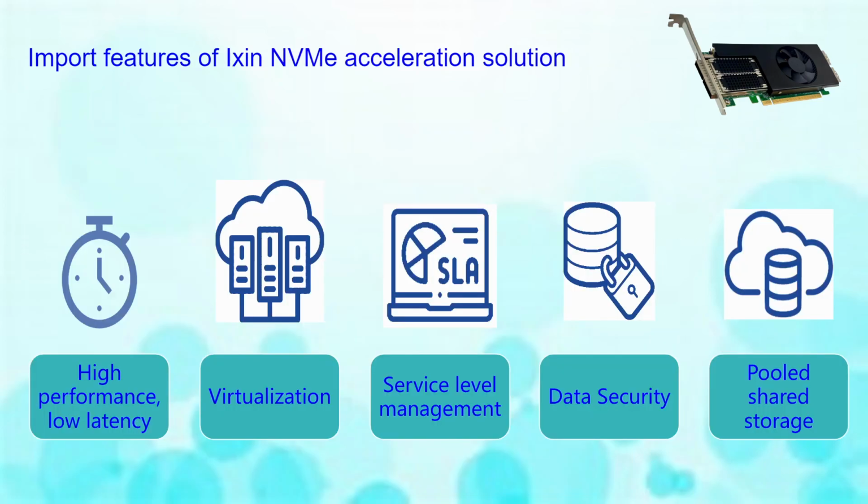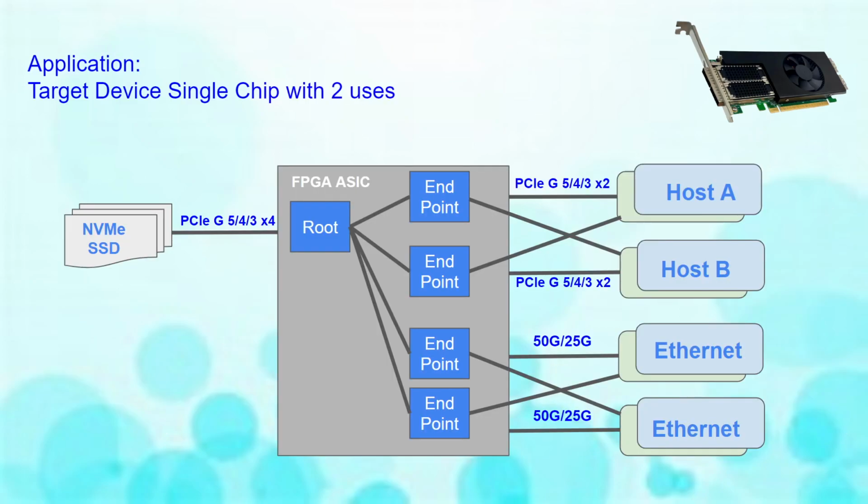Here are the NVMe acceleration solution features. Here is a sample application supporting two PCIe Gen 5, 4, or 3 hosts and two Ethernet 50G or 25G from the endpoint with one NVMe SSD through PCIe Gen 5, 4, or 3 x4 from the root.